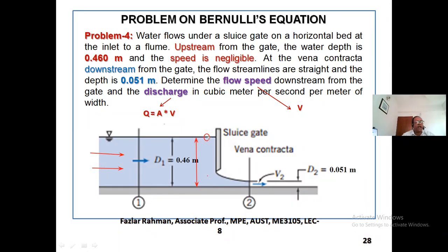So if you are not able to maintain this height constant, then what will happen? The pressure energy changes, since water is coming out through the bottom portion, so this velocity V2 will fluctuate. So your turbine blade will not rotate at constant speed. It will fluctuate from time to time. So that's why in a hydraulic power plant, they always maintain a constant height.